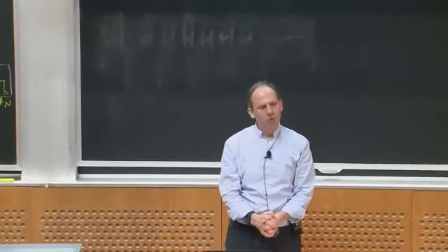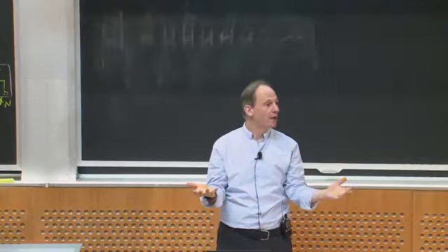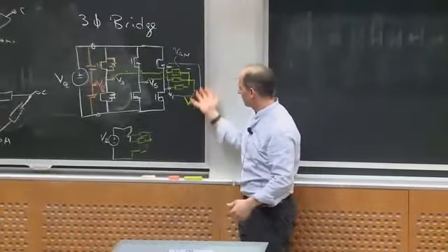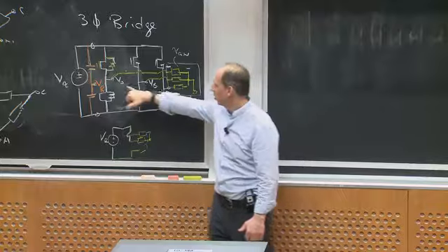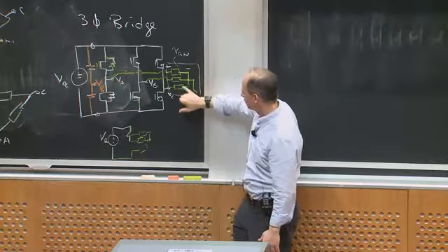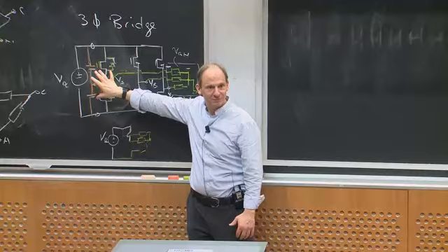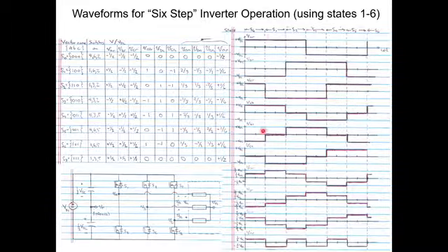Okay. What would it do as regards the line to neutral voltages? Well, we said this thing's basically a voltage divider, right? But I could think about the neutral voltage as being sort of the average of VA, VB, and VC. Essentially each of VA, VB, VC has a fundamental, and then it has, for example, a third harmonic, because it's a square wave.